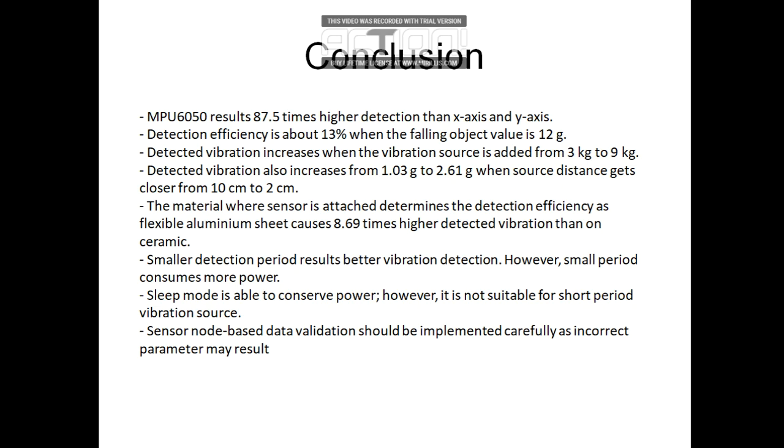Detected vibration also increases when the distance between the vibration source and the sensor is closer. The material where the sensor is attached influences the detected amplitude. The flexible material produces better detections than the solid material like ceramic.